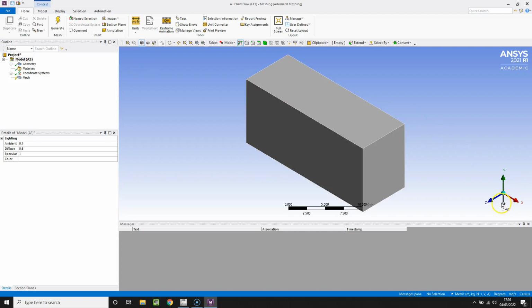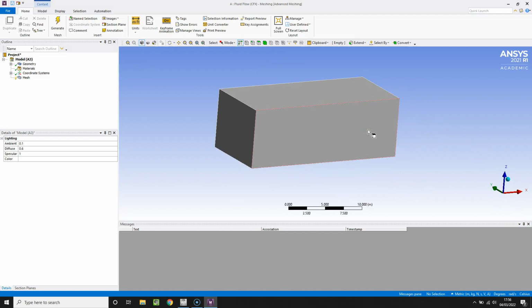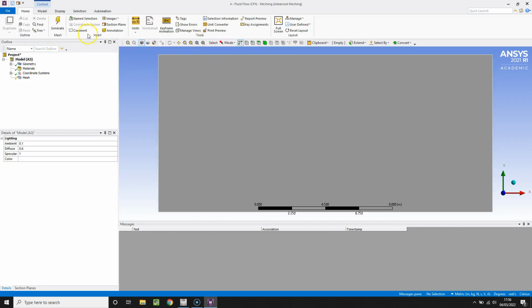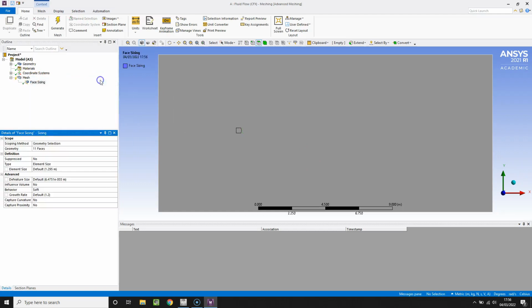Okay, so I'm not going to create a particularly intense mesh here, and the reason being is that we're going to make some changes to the geometry as the simulations run. So to keep this cost effective, keep it simple, keep it quick, just going to add a quick surface refinement. So viewing from the top and seam to selection, and just selecting a box, select here, find your Ahmed body, right click, insert and sizing.